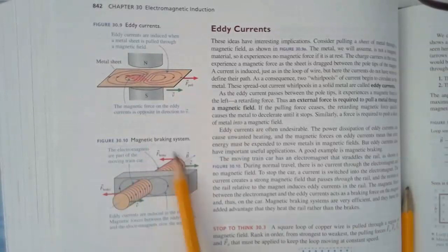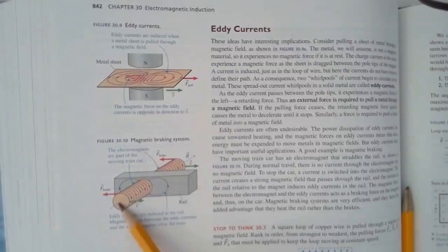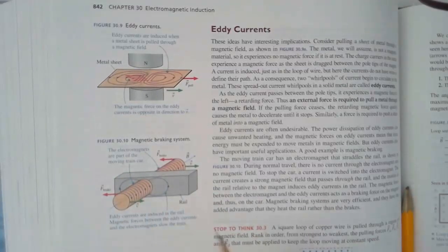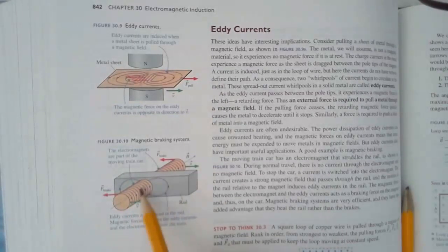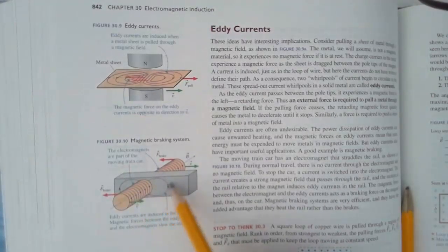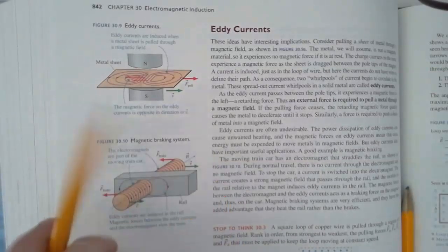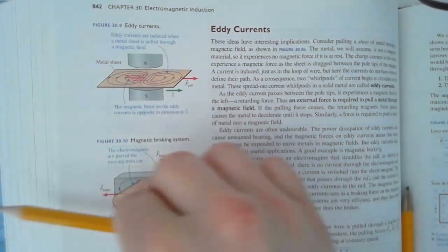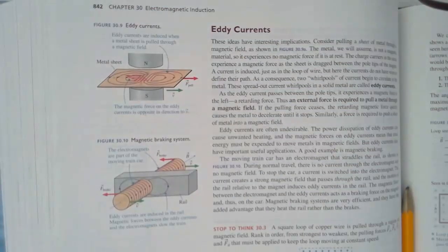So here's the picture for that, in the magnetic braking system, where I have magnets, and they might be like electromagnets, and they move. Like this would be the rail, right, on which the train is running, and those are not touching. So left and right of the rail, and it moves this way, and then I turn those into magnets. I'm going to get eddy currents in the rail, and the eddy currents then want to push the rail forward, and so similarly the train gets pushed backwards by Newton's third law. It experiences a braking force.